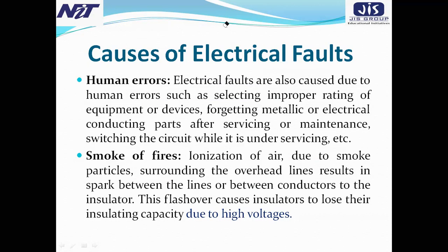So electrical faults are also caused by human errors, such as selecting improper rating of equipment or devices, forgetting metallic or electrical conducting parts after servicing or maintenance, switching the circuit while it is under servicing, etc. So it's a huge risky area also.